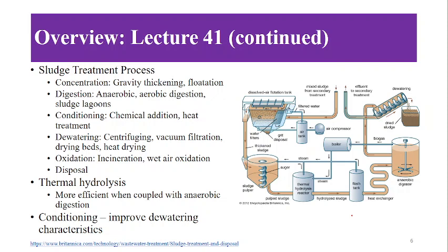And next is dewatering. Dewatering is done through processes such as centrifuging, vacuum filtration, drying beds, and heat drying. And lastly, the oxidation step is there, in which incineration of this sludge is done, or you can go for better oxidation. And finally, the disposal of this treated sludge.